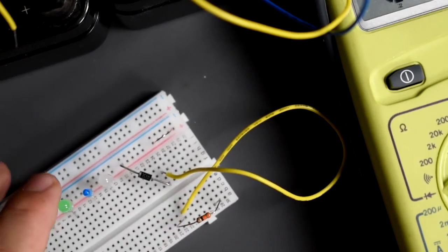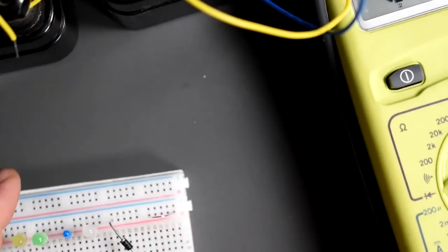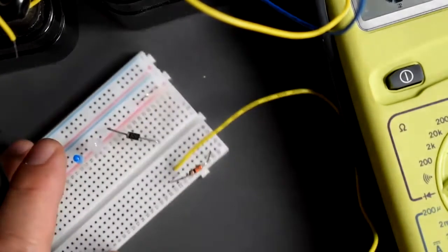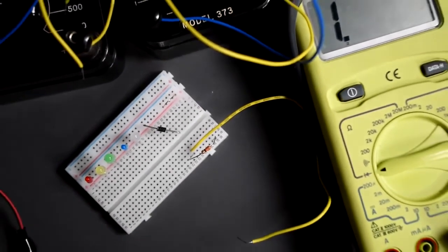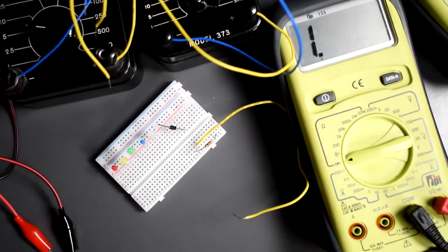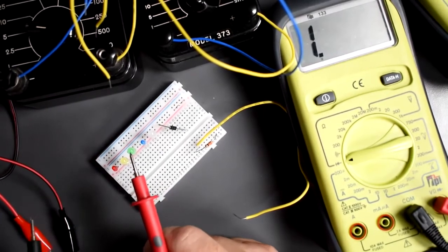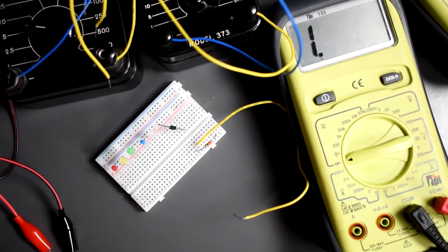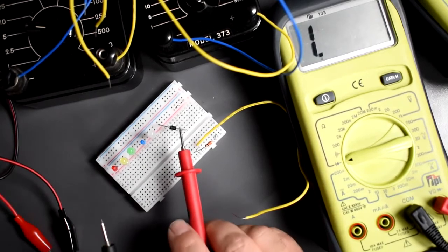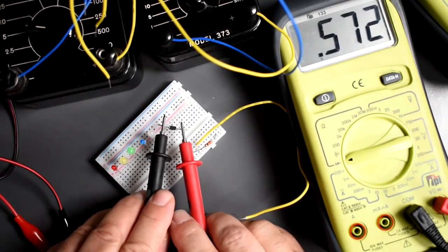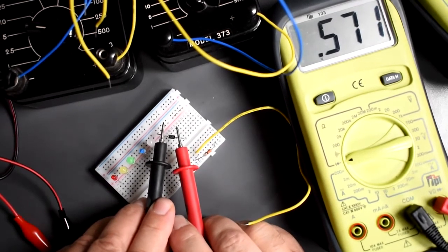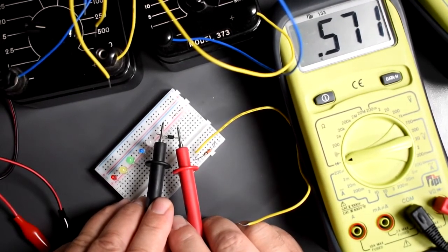Okay. Now let's take that diode out of the circuit. So it just sits right on its own. And we're going to forward bias that diode. This is a silicon diode. It should have 0.7 volts when it's forward biased. So here's the positive, here's the negative. Let's touch that, see what happens. Well, this one shows almost 0.6. So it's close to 0.7 of forward bias voltage.